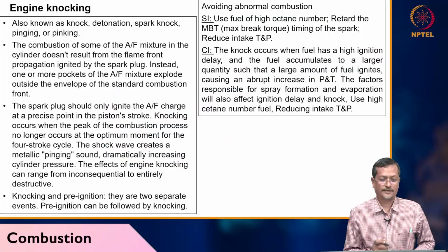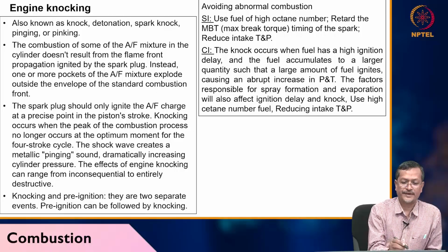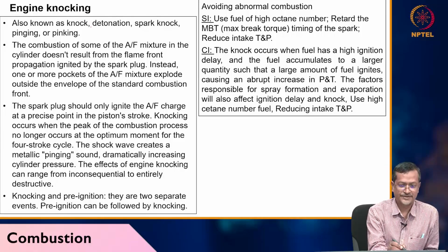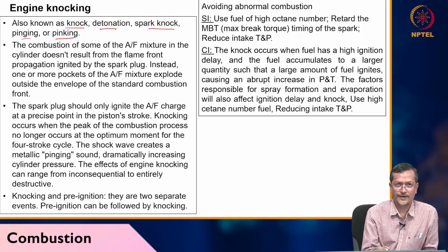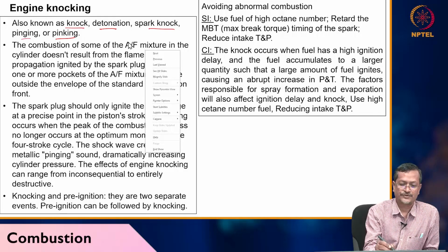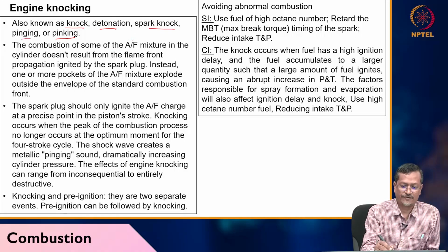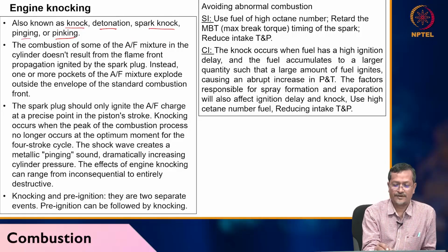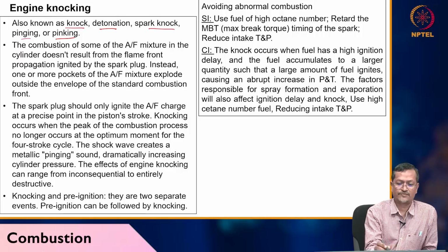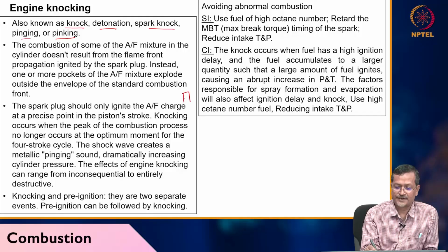Now engine knocking, this term is very familiar to IC engine designers and IC engine users. This is called knock, or detonation, or spark knock, or pinging, or pinking. Different names are there, so you should be familiar with the different names. Combustion of some of the air fuel mixture, here every time I'll be writing A/F to mean air fuel mixture, in the cylinder does not result from the flame front propagation ignited by the spark plug.